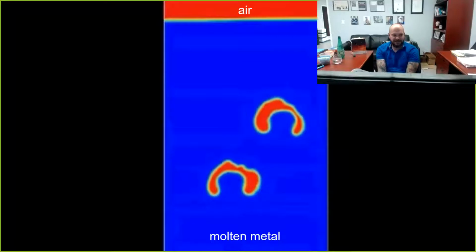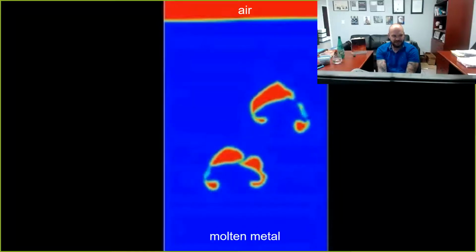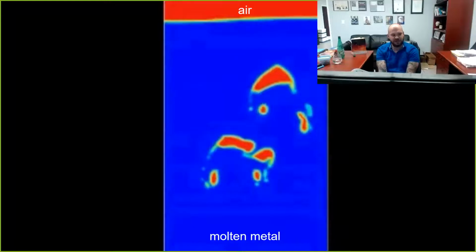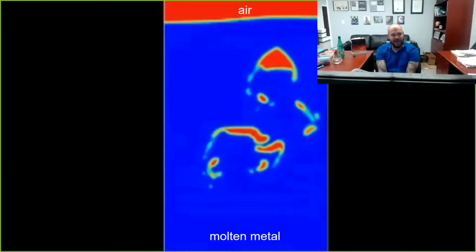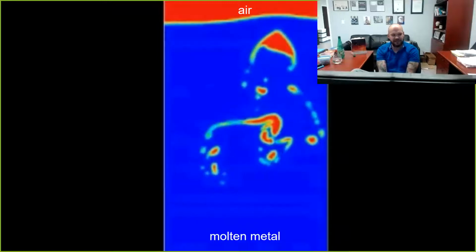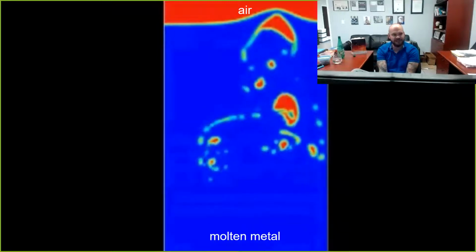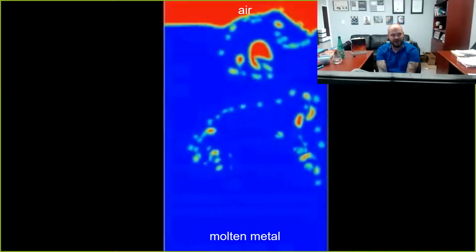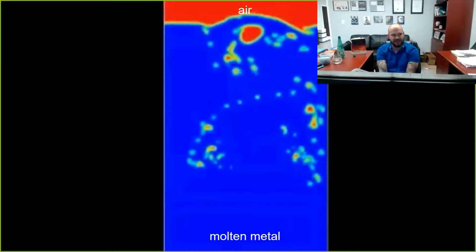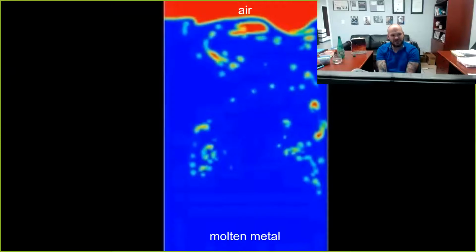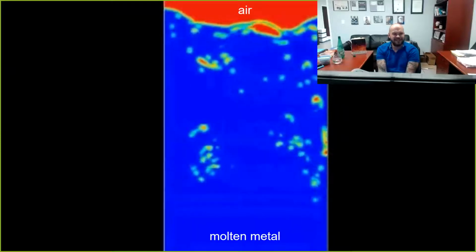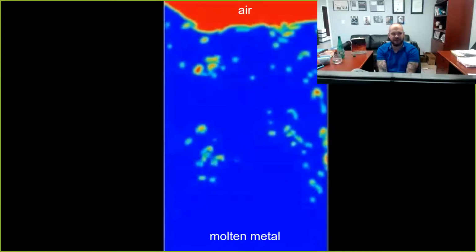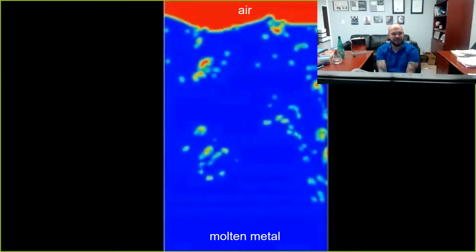You'll notice instantly we get microscale turbulence and vortices at the shear zones. You can see the air being consumed and turning into oxides. You can see that what happens now is that as the oxides are being consumed and getting thicker, they become neutrally buoyant and trapped in convection currents. You can see on the surface now what we've got is an oxide film against an oxide film. And so now we've got a surface lamination or an orange peel type defect. And you can see now from those 2 little air bubbles, we've got literally dozens and dozens and dozens of small little locations of non-bonding within our metallic matrix. And this is from 2 little air bubbles. Forget about thousands and thousands and thousands of them during the life of the core.